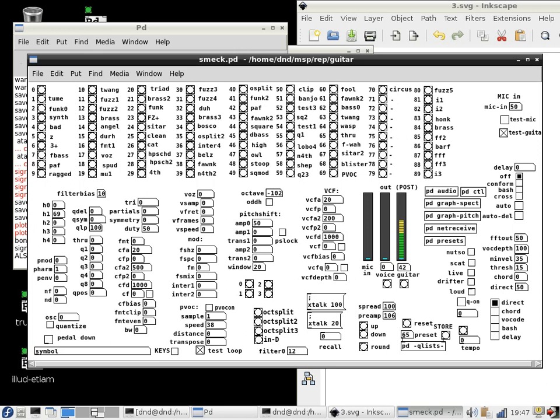And then if you want to go down an octave, just ring modulate by a tone that is half of the fundamental frequency. And then you can take that down 2 octaves if you really want to. Actually, you could take it up 2 octaves if you cared to. And that's something you do without any of this high-tech stuff I was just talking about with the unipolar. You can just do that to any signal that you can determine the pitch of.